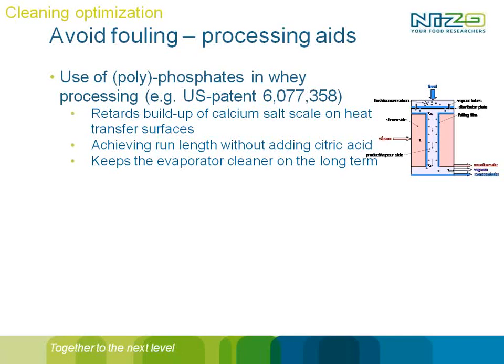It can also serve as a matrix for microorganisms. And by the use of polyphosphates, you can retard the buildup of these calcium salts, so your runtime is longer, your evaporator remains cleaner in the long term. So this is one way to improve your process.